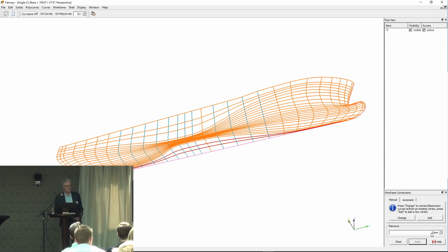That's always a bit of fiddling, because even a NURBS surface or an IGES file exported from Rhino, or from any other software, does have limited accuracy, always. And on reading it, we have our own setting to find the connections between points, because as it is now, they are unconnected wires. If I do that, I press automatic, and here they are being recognized, inserting points at intersections.